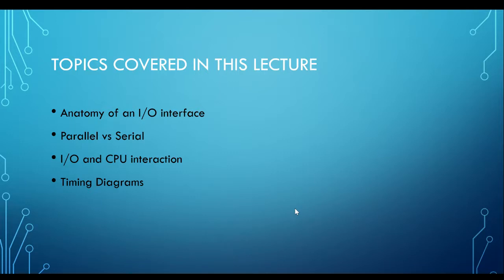And serial processing, sending information through serial, is another alternative which reduces the number of pins. Your USB, for example, is a form of serial communication. Although you may not know it, serial communication has gone through a lot of alterations and evolutions. What we have today, I2C, SPI, USB, are all from the same technology. They call it serial processing. In fact, I'd like you to look at a few very important ones, namely the UART. UART is one of the very important and very basic serial communications.